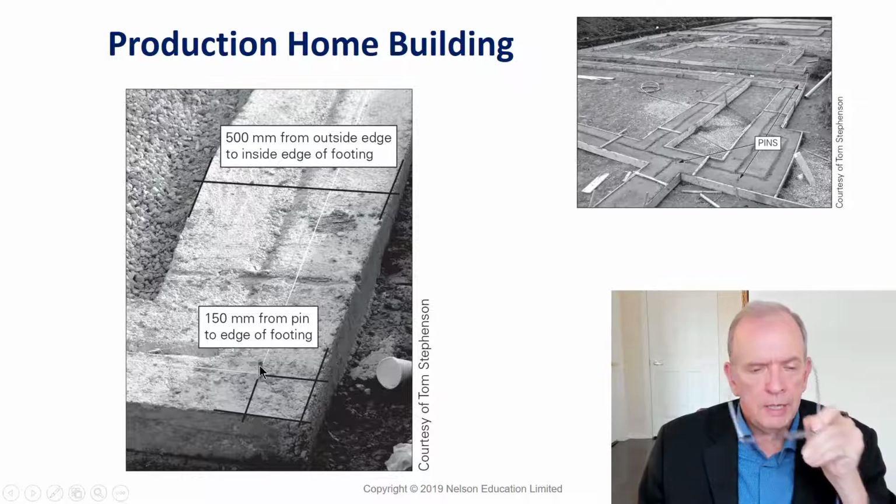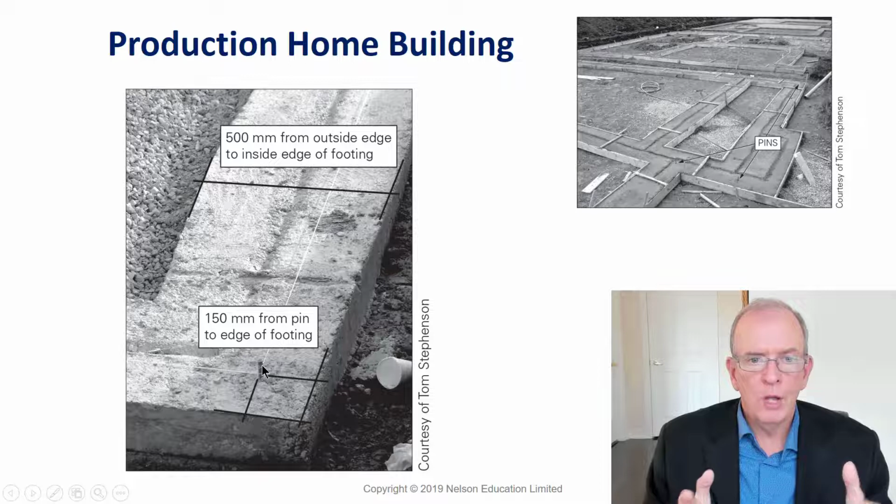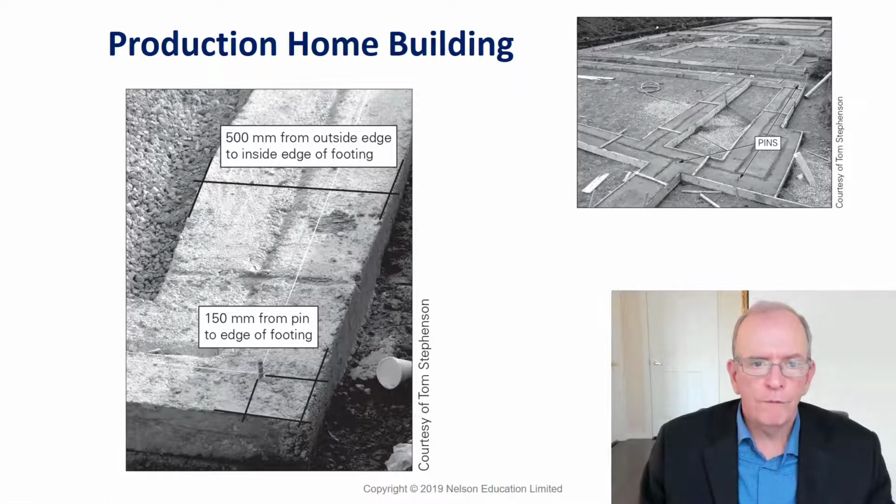And usually what happens is you see these little pegs here. The builder or the developer, they're going to get an OLS, a registered land survey, or whatever your province is, whatever your area. So we call it OLS, Ontario Land Surveyor, and they're going to put pegs that will be based on the site plan to show how far set back the actual finished wall for the house is going to be. And then if you know the size of the footing, it's just measured from those pegs.